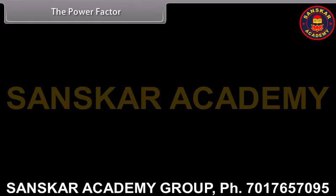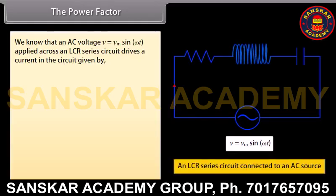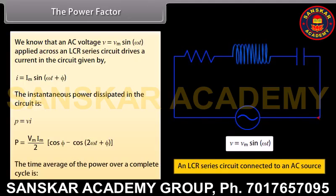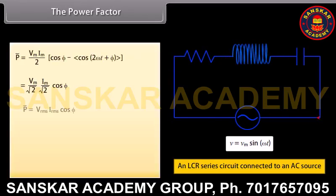The power factor. We know that an AC voltage V is equal to Vm sin omega t applied across an LCR series circuit drives a current in the circuit given by Im sin omega t plus phi. The instantaneous power dissipated in the circuit is P is equal to Vi. The time average of the power over a complete cycle is given by Vrms into Irms into cos phi.